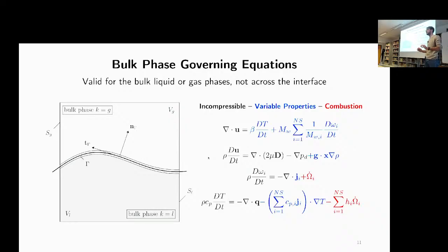But it's a very approximated version of radiation modeling, and I use it just for combustion cases. It's valid only under the optically thin assumption, which means essentially that the flame is thin and the optical thickness is less than 1. In this condition, you can assume that the radiation effect is just a heat dissipation.